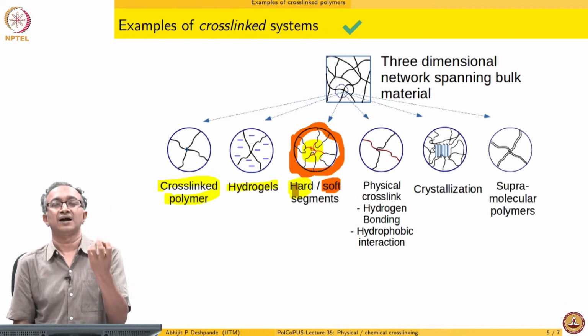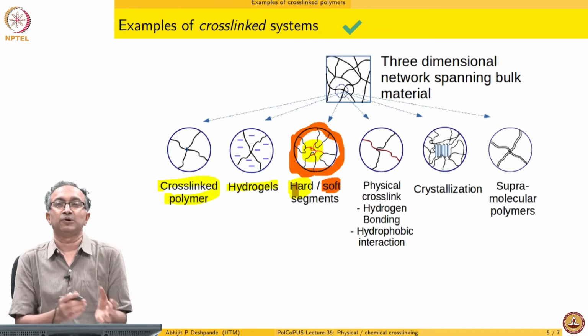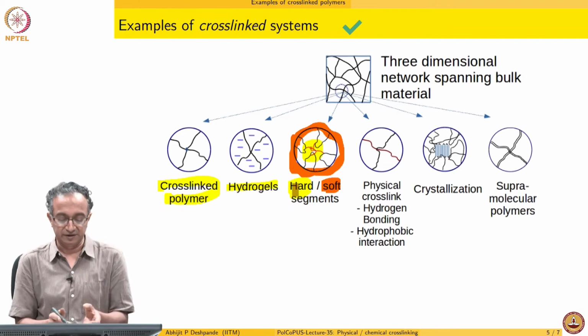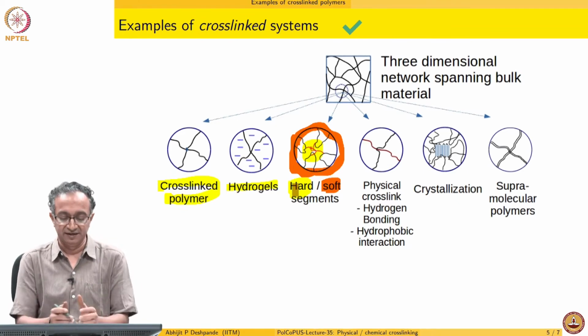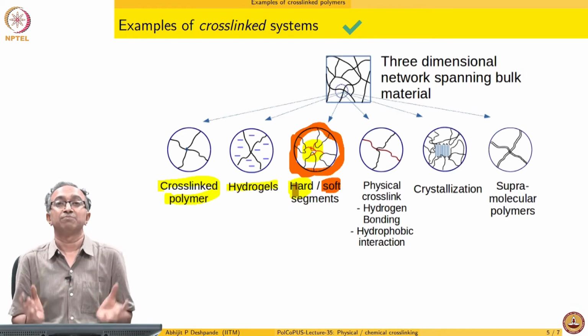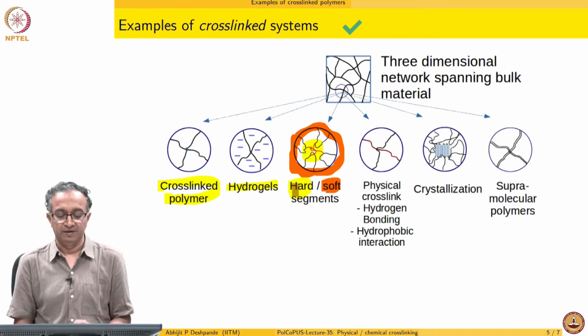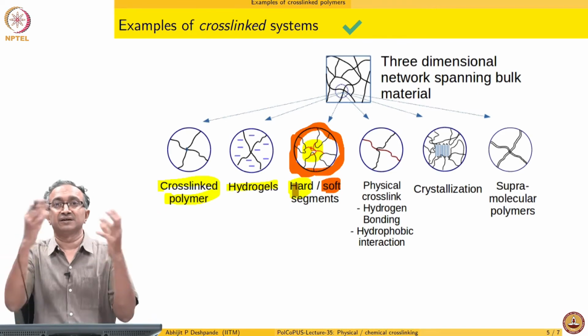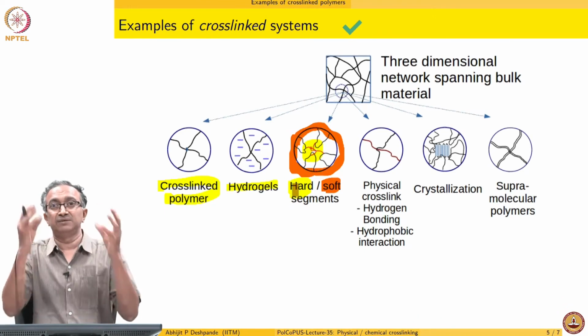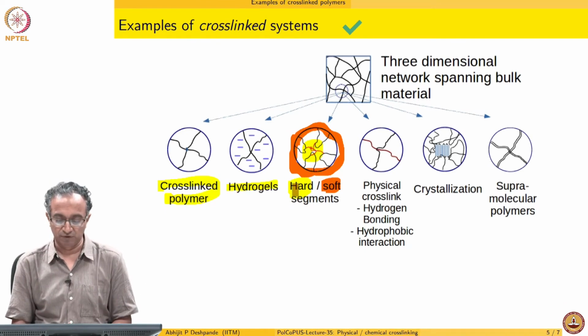So this hard point, for example, polyethylene, polypropylene. Wherever red polypropylene chains are there, they are surrounded by black polyethylene flexible chains, and the red polypropylene chains will try to act as a crosslink point, keeping together fixed the polyethylene chains which are more flexible.